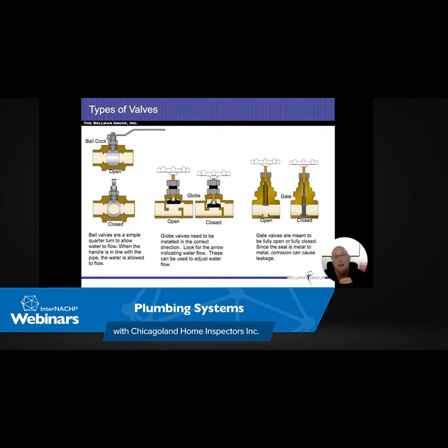The term waste gets used for water only or liquids only. So if it's a kitchen sink or it's only a slop sink or a laundry sink, those are waste lines. All right. So it's either a waste pipe or a waste stack. Anything that's horizontal is a waste pipe. Anything that's vertical is a waste stack.